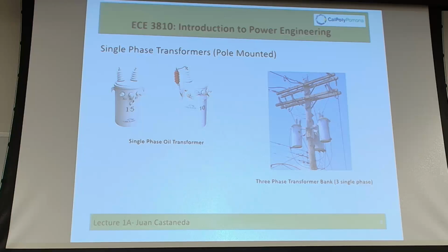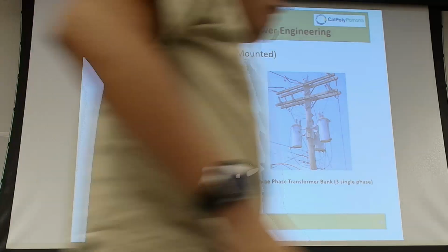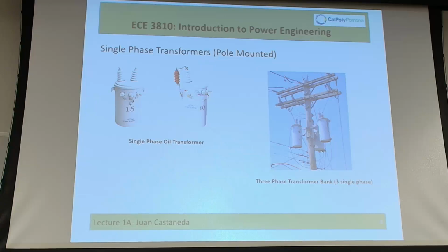So that's why utilities now, especially in the state of California, are starting to push for ester fluid. Southern California Edison as an example, and PG&E and San Diego Gas and Electric, especially in high fire areas, have gone as far as proactively taking old transformers with the conventional oil and replacing them with FR3 or ester fluid.